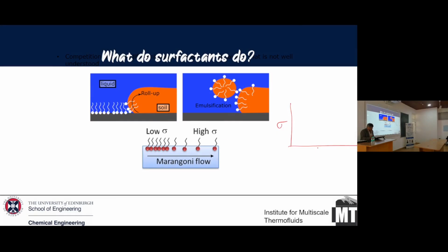So if you look at surface tension with respect to temperature, typically for most pure fluids, it's a straight line, and the slope is determined by the thermal Marangoni coefficient. Okay. In some cases, for example, if you have a water-butanol system, this is a mixture, so your surface tension and temperature profile is slightly different.